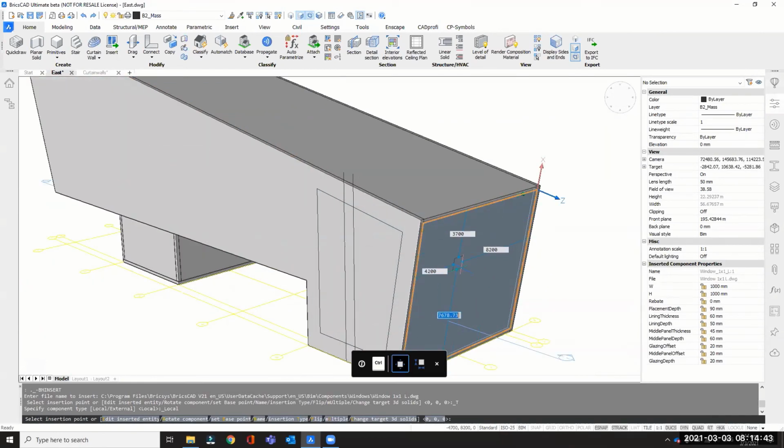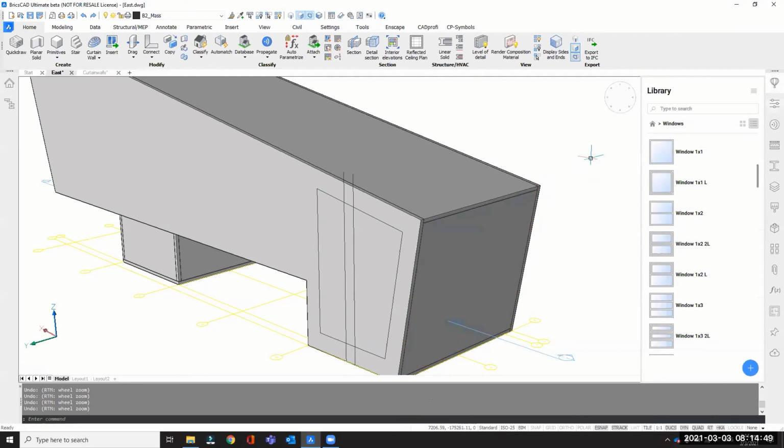in your model. So one of the other ways to also insert a certain component, aside from the ones in your library, would be calling the quad cursor from an empty space in your model space. So I'll just right click here. So I have the quad menu, and you would be able to find this BIM component, BIM insert.